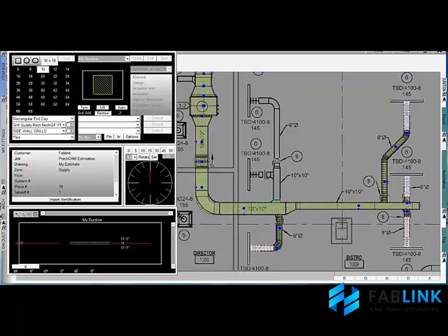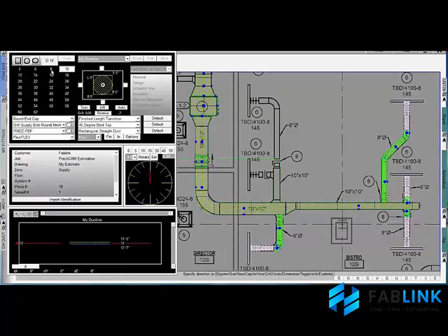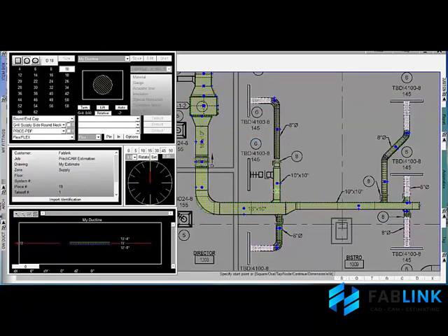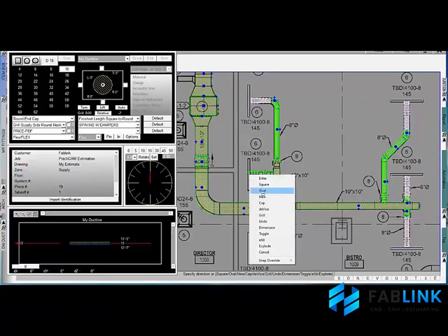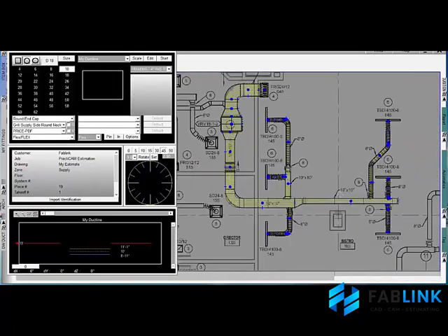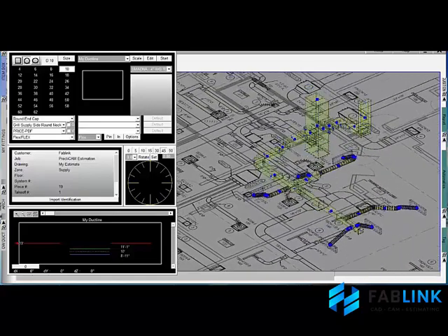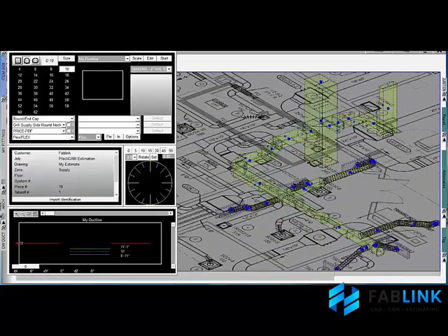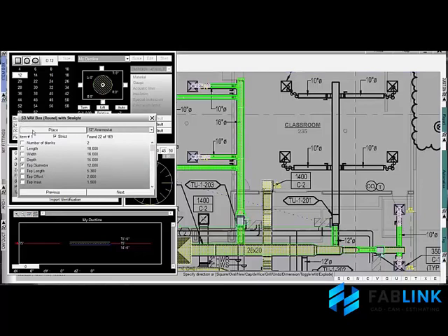Fittings can be logic-driven to automate which one gets used where. GRDs can be automatically generated at the right elevations and connected with large varieties of choices between flex, pipe, collars, grill cans, and more. Elevations are automatically created and accurate, whether you're drawing a riser straight up and down or sloping between points. Even roll angles are easy to estimate and draw within plan view.